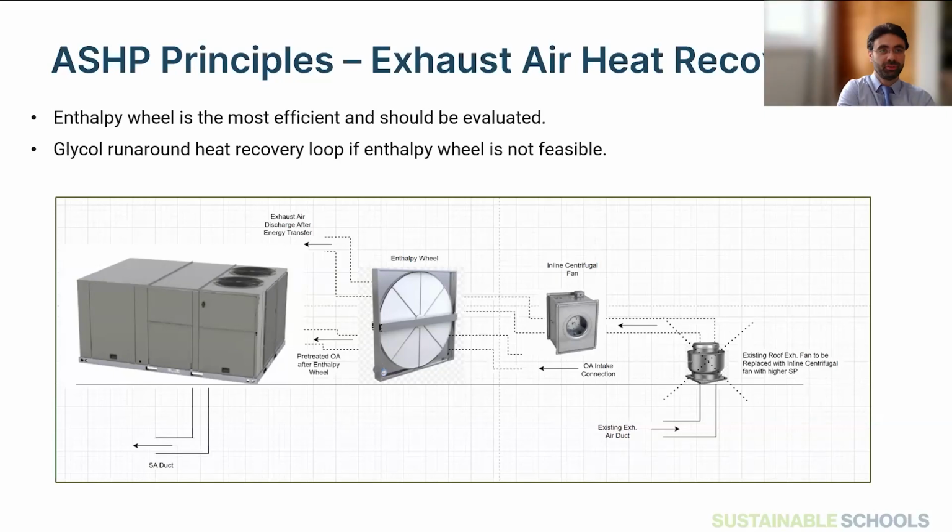Let me clarify one thing first, because there is something called fixed temperature switchover, which is a balance temperature where a gas operation would start to be more efficient. However, there's a low temperature cutoff. I think this is what you're referring to, when the units can no longer run. And this is typically nowadays getting closer to -15 degrees Fahrenheit